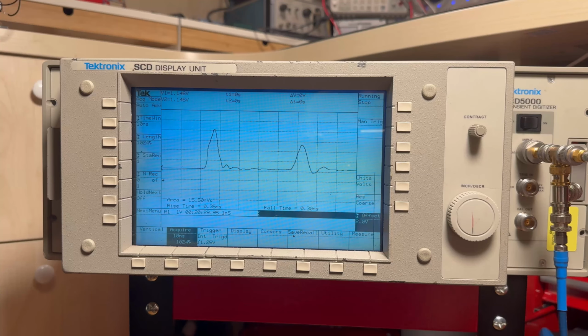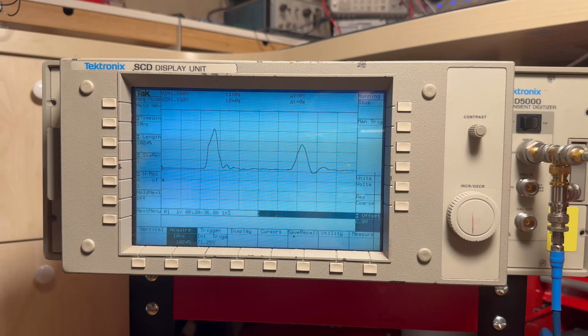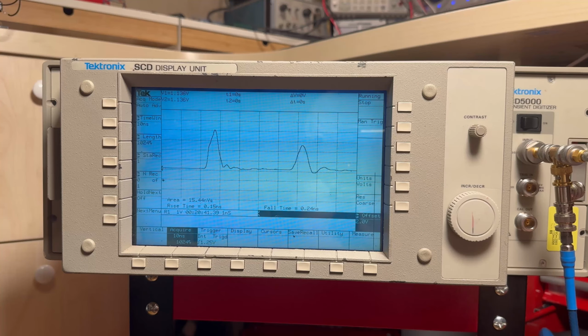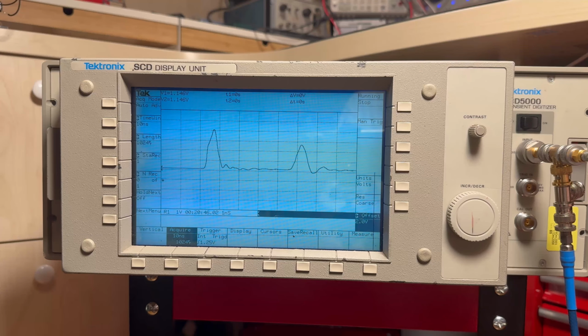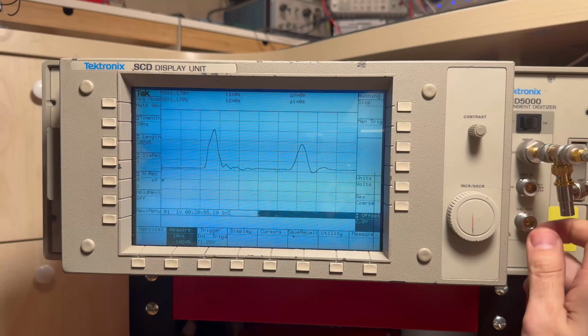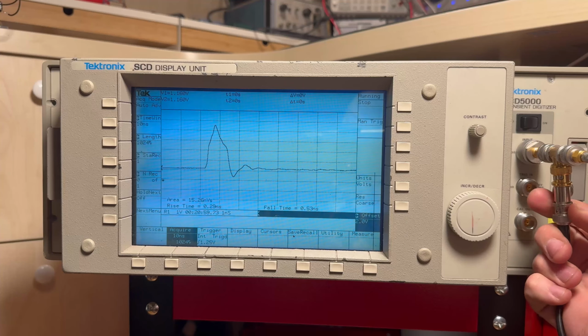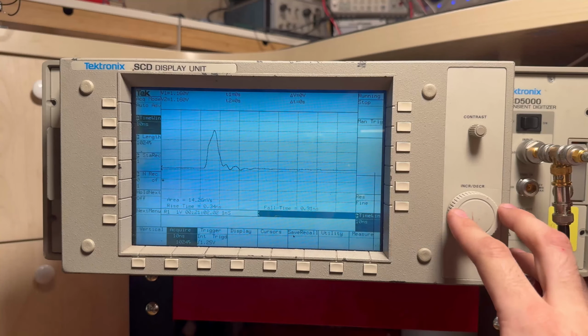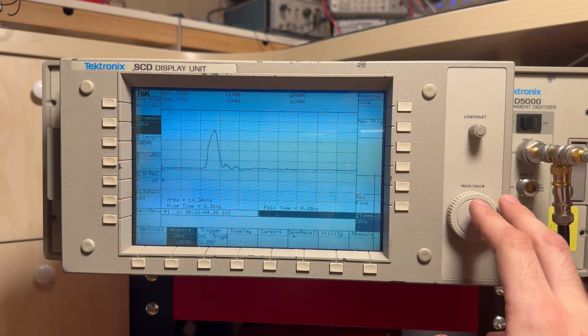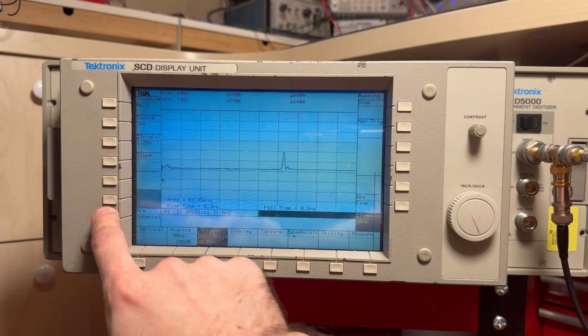So if I had a cable that was half a mile long, I don't think I could have had enough memory to see it with this, or resolution or whatever. But if I had a cable that was 10 meters long, then I could have seen it. Let's actually look for a longer cable and connect it instead of this, and maybe increase the length of the interval between the two pulses. Apologies, this is all very impromptu. And I think we're gonna need a longer time window, so 50 nanoseconds, and let me just delay the trigger a bit,